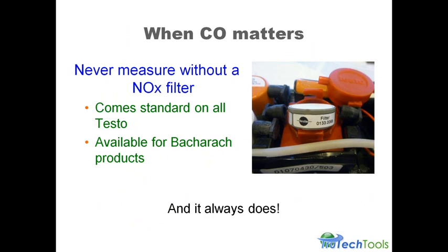And that filter will last the life of the CO cell unless you're getting something that's got a ridiculous amount of NOx in it. And if you throw it on test gas, at TruTech when we're doing combustion tests, we actually order our test gas as a combination of CO and NOx, so we can test the NOx filter. And it's available as an accessory for all Bacharach products. So if you own a Bacharach meter and it's not the Insight, you probably need to order a NOx filter for it. And it's like $45. You just throw it in line, and it strips that NOx out, and it gives you a true CO reading.